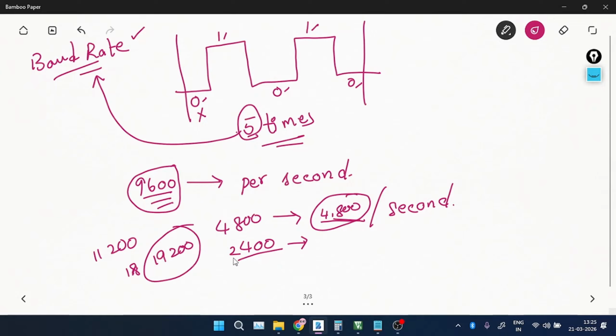For our experiment purpose, we are going to check 2400, 4800, and 9600. The interesting fact here is, in order to establish this baud rate, you have to go back to timers. Again, you have to know the basic timer calculations, that is the timer frequency, and then timer tick period, and then what we call counts, and preload value.